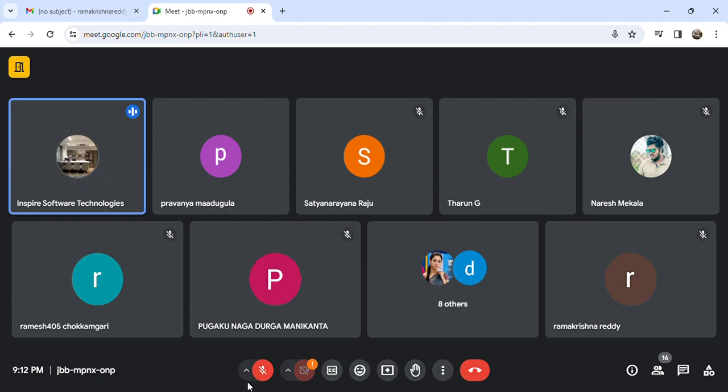Okay. Explain the data frame. If the question comes like this, can you tell me what fields are available in the data frame, or can you explain about the data frame, then you have to start from the start of frame. After that, the arbitration field, then the control field, then the data field, then the end of frame. You have to tell all the fields. I intentionally skipped the acknowledgement field and CRC field. Nobody is telling them, but you have to practice that, and people who are using it will know that all these fields will be there.